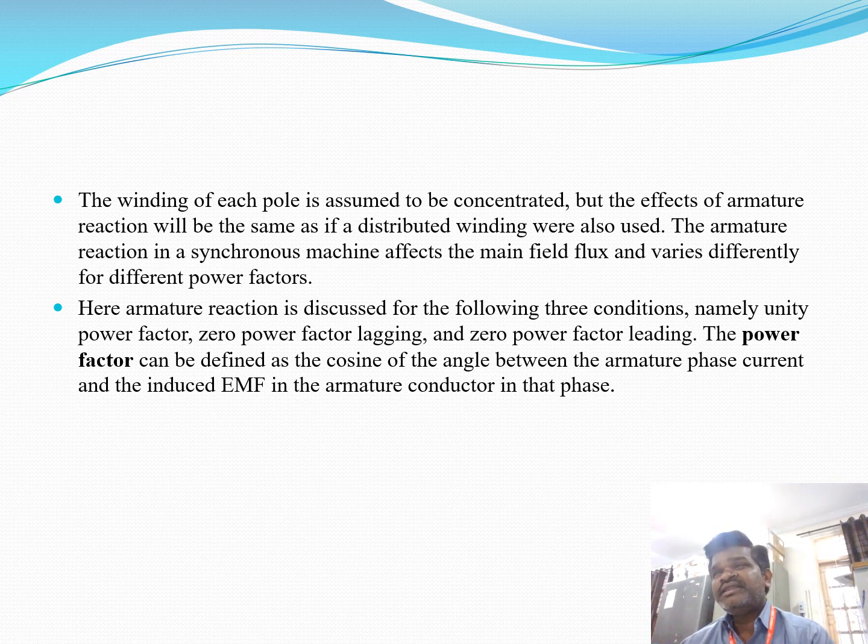Means the armature reaction effects change depending on the power factor only, not on the type of winding we are using. Either concentrated winding or distributed winding you can use. Now the effect of armature reaction changes depending only on the type of power factor and magnitude of the current.